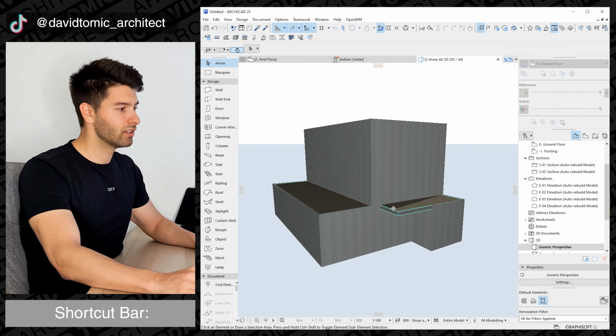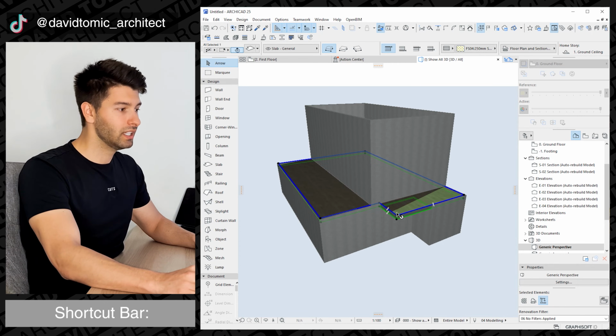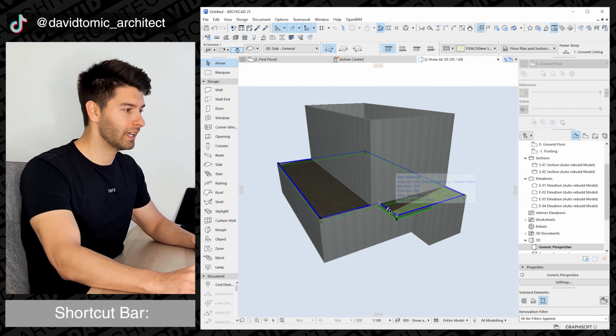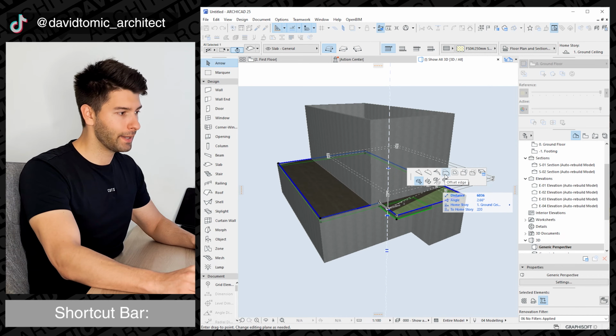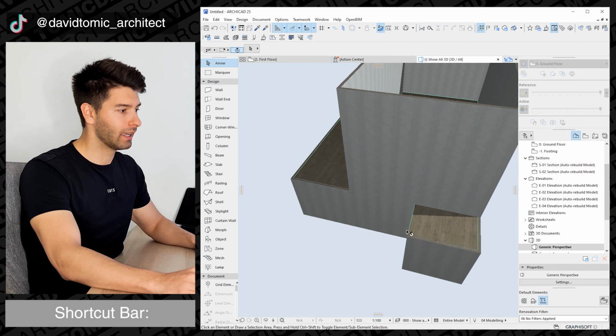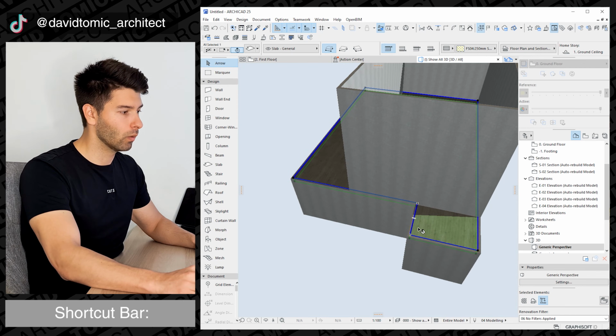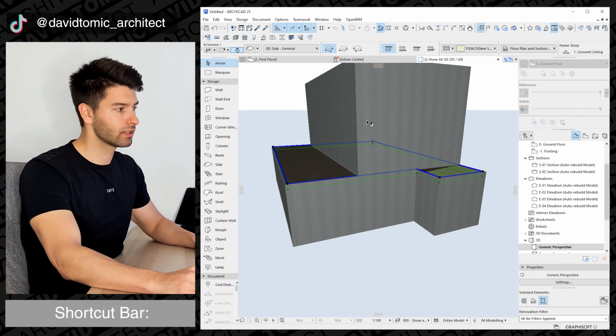So as you can see, there's a few things that are wrong in this 3D scenario. First of all, this floor slab we haven't adjusted to our new walls. So we can do that in 3D by simply clicking on this slab, clicking on the blue line, coming across to offset edge and running it all the way back in line to the edge of our wall. And we want to make sure that we're on the inside so it's the same as everything else.